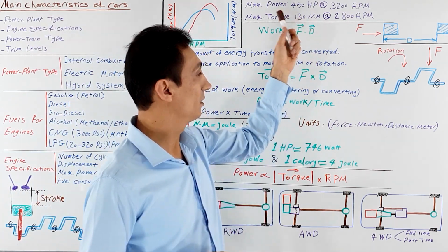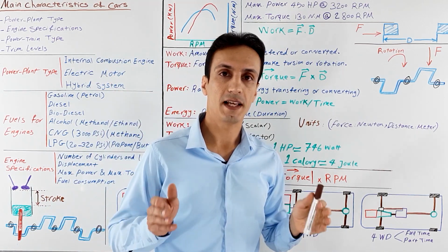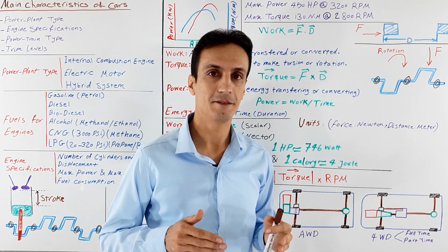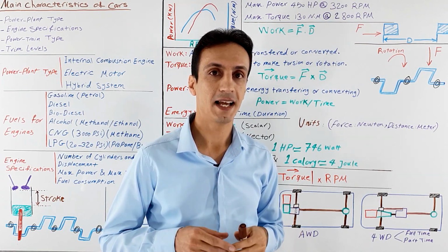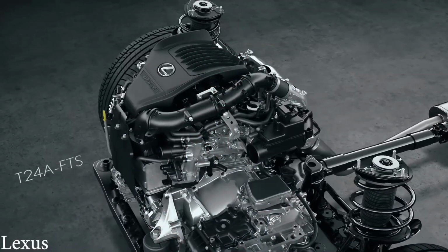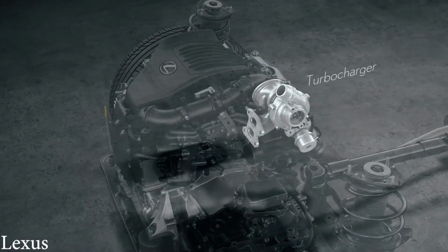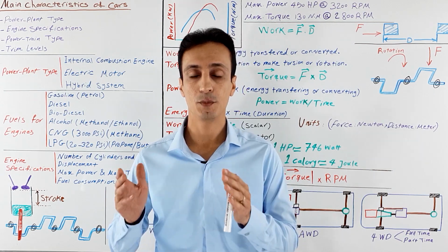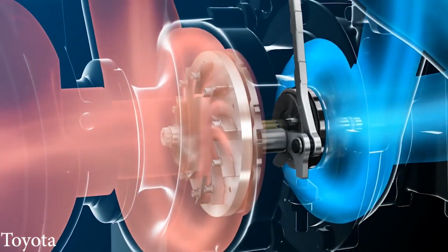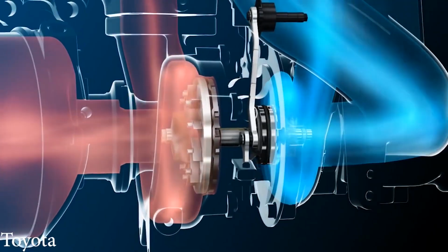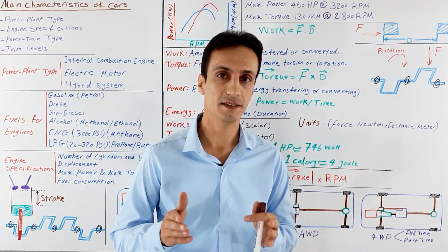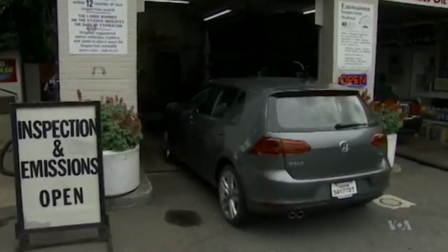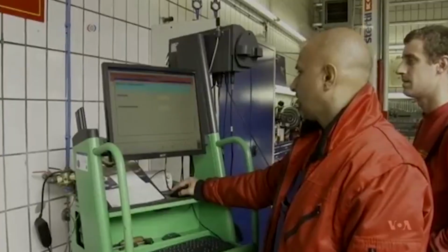To increase these numbers, you can use turbochargers and superchargers, and an engine with a boosted air supply system, and fuel consumption as a compromise, has better performance under load. This boost system can be designed by the engine designer or by aftermarket suppliers, and they come in a package called a boost control system. This boost control system is relatively expensive and takes its toll on the engine's life, and also installing them at aftermarket shops needs ECU reprogramming that may affect emissions.